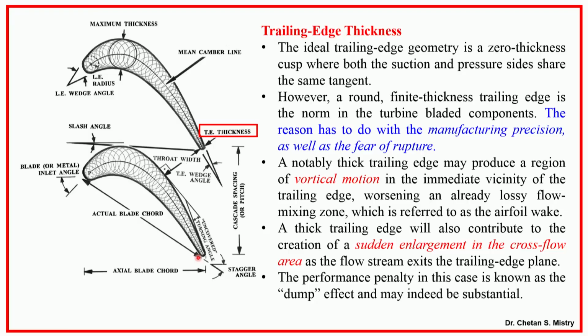Now, let us try to understand what exactly is happening here. At the trailing edge, I will have one flow coming from my suction surface and another flow coming from my pressure surface. They merge together, and because of the blunt surface, it generates my wake. We have seen in the morning that this is my negative wake.